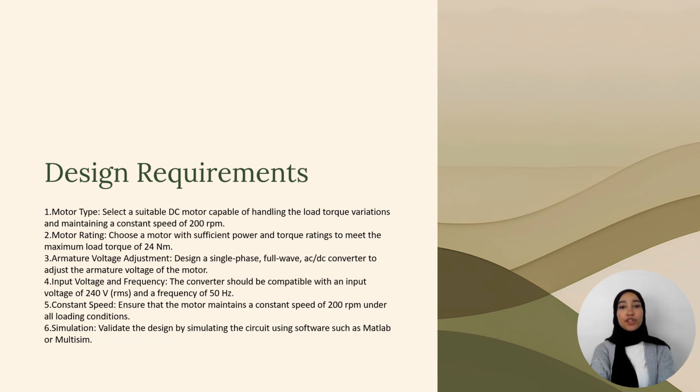Third is the armature voltage adjustment: to design a single-phase, full-wave AC to DC converter to adjust the armature voltage of the motor. Fourth is the input voltage and frequency: the converter should be compatible with an input voltage of 240 volts RMS and a frequency of 50 Hz.